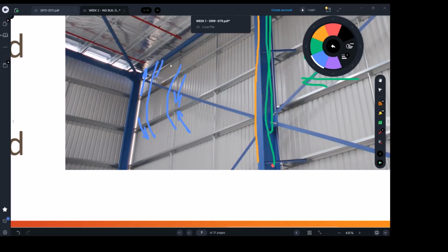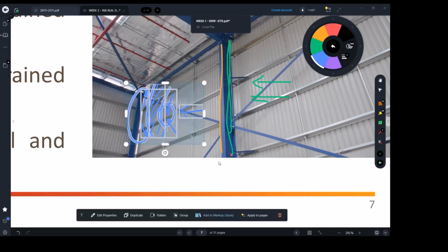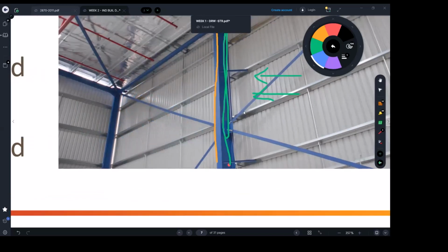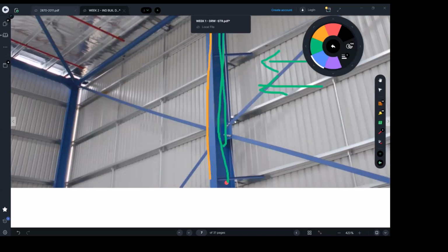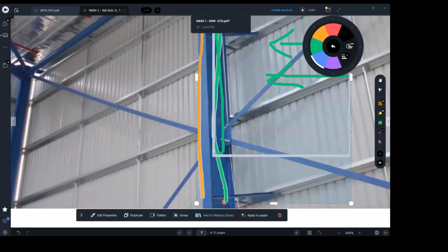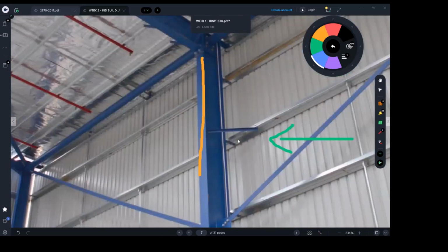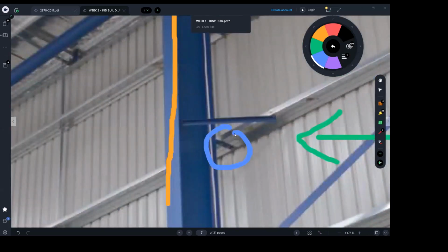Okay, so this is your beam. When you're gonna be putting a pressure this way, outside in, you're gonna be flexing it, curving it like that. Usually this side gonna be under compression, and this side is under tension. Now, one thing I want you to understand, the beams are very sensitive to compression because they're gonna buckle. If you over compress a flange, it's gonna buckle. And that's why, to prevent that buckling, we're gonna have the girts helping that beam or flange from getting buckled.